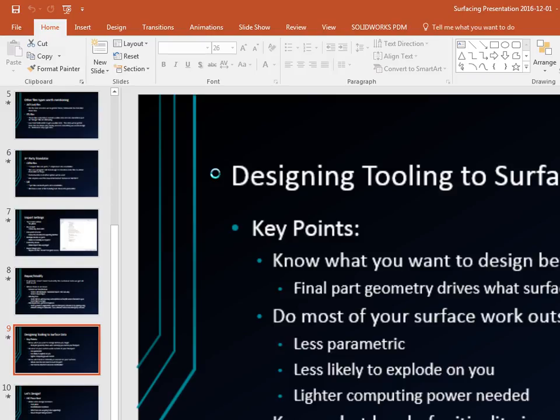Let's see, any other fillet options we should talk about? Tangent propagation. Let me scroll back before I filleted. Sometimes I've got this whole outer edge that's tangent. If this one particular edge that I have highlighted is an issue, I can just turn off tangent propagation, go back to normal fillet here, and take only a couple of the edges.